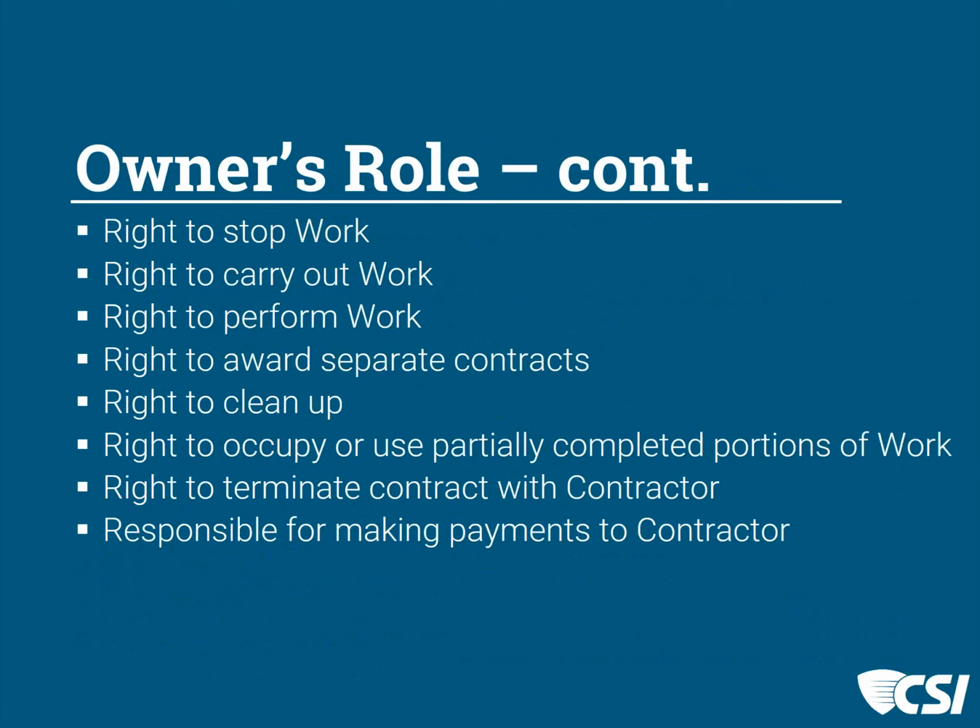They can carry out the work, perform work, either themselves or through separate contracts. If the project's not being kept clean, they have the right to do that. They also can occupy portions of the work if they need to do so in order to advance their opportunities, and can partially occupy and use the project. They also have the right to terminate a contractor for due cause if it comes to that.